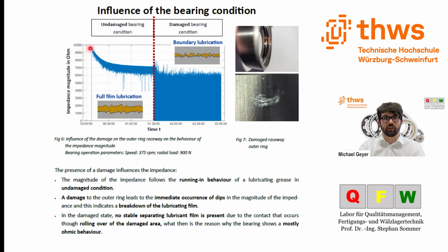In the presence of a separating lubrication film, as shown here, the electrical behavior can be described as an operation-dependent parallel circuit between the resistance of the mainly lubricant and the capacitance consisting of the capacitances of the inlet, outlet zone, and the Hertzian area. Changes occur, however, on metallic contact between the contact partners, where the capacitance of the rolling contact is short-circuited by the low ohmic metallic components.